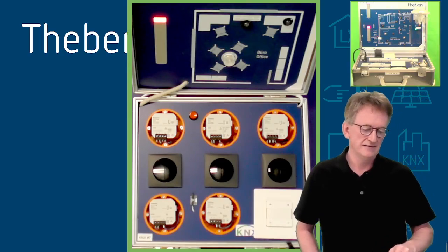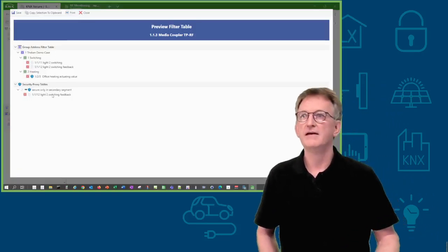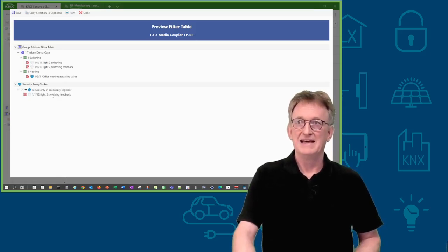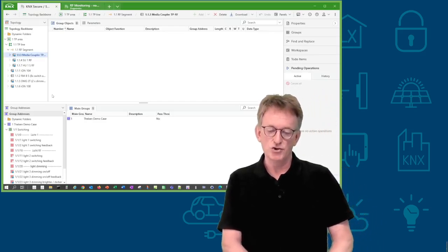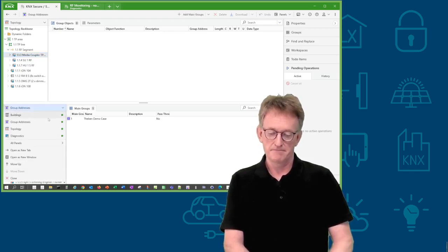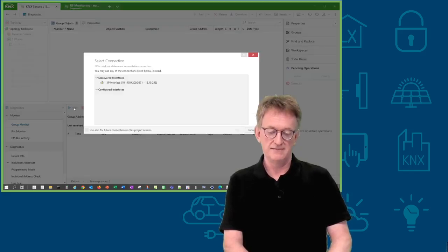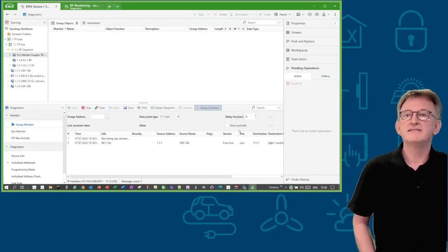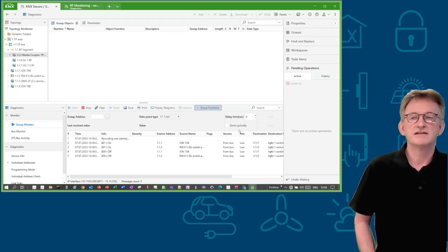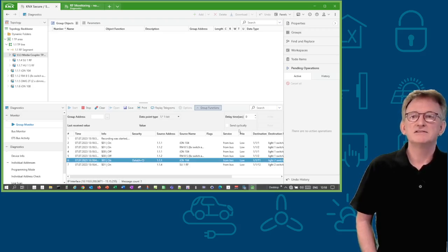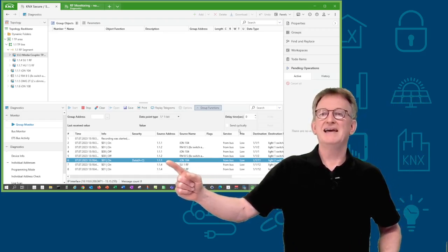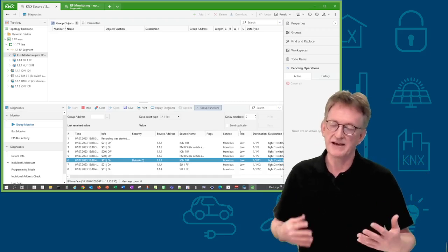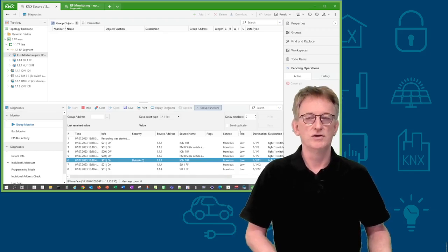And that's exactly why this group address must be converted. But also, what I would like to show you, when I'm looking in the diagnosis, you can see here the commands I'm sending. I send here the local, that's on, that's off, that's local unsecure. But also now here you can see the blue, which has been sent as data secure, and the feedback is unsecure. But we are still in the same project, and so ETS will decrypt that secure telegram.